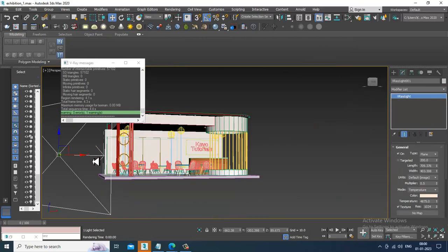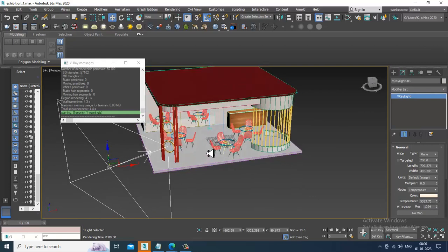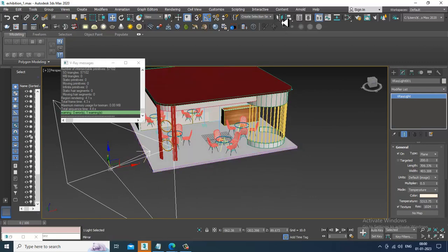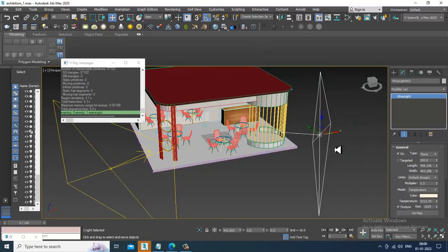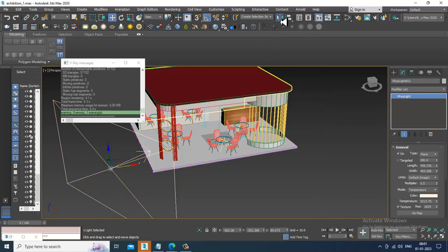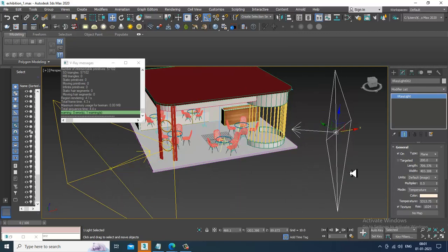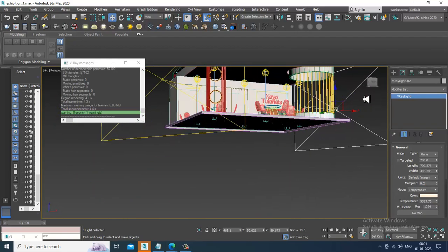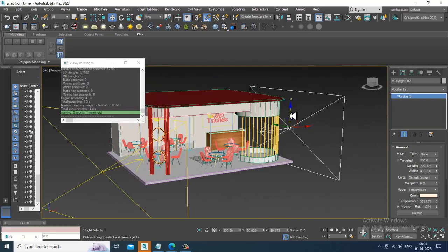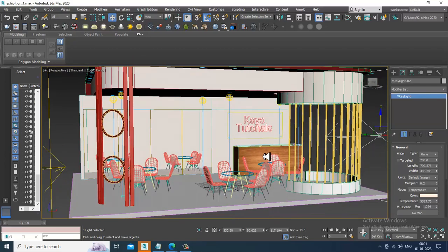Select this light again and let's set the temperature towards a bit white. Select this light, let's mirror it, copy it in the x-axis. Let's reduce it to 0.2 over here, and we can slightly shuffle this light on this axis. We also need to set a camera. We have not set up a camera.